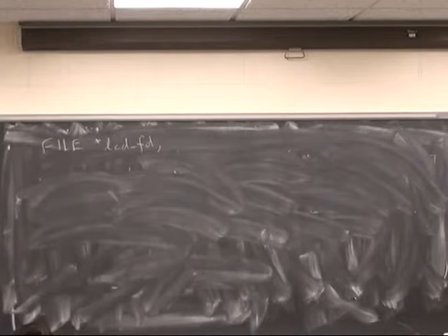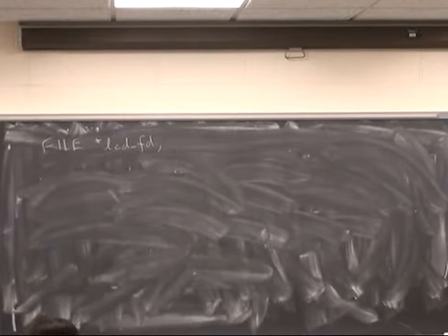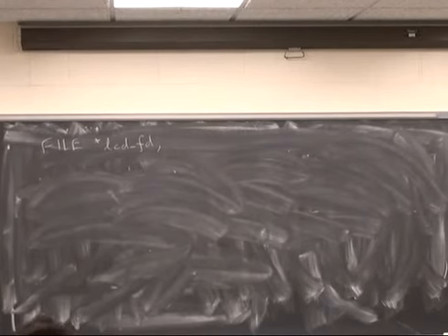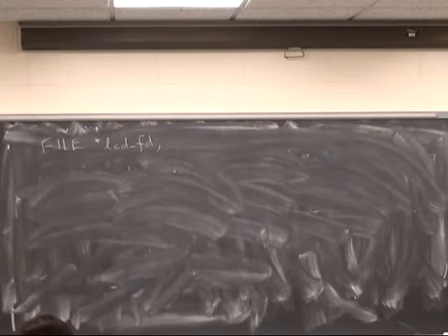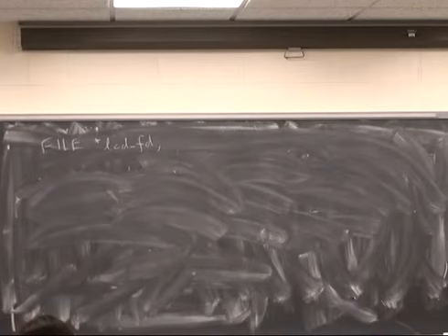And now we can do this in various orders, but let's write the interrupt service routine for the timer. And we need a timer here because we want each note to last 1 second. So we're going to play middle C and then D and then E and go on up, and we want each note to last 1 second, so we need an interrupt routine to time out 1 second.